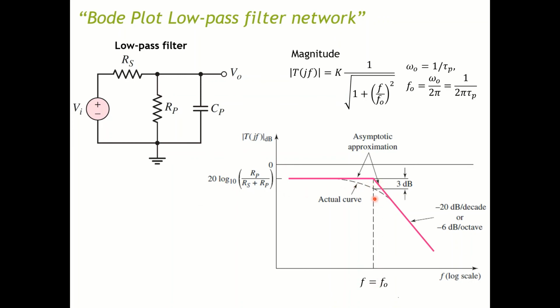In the same way, remember the high pass filter, the gain increases, then flattens out, right? So higher frequency is allowed to pass through the filter, lower frequency is not allowed, and the transition happens at the corner frequency. The low pass filter also works in the same way. Low frequency is allowed to pass through, but high frequency is not.